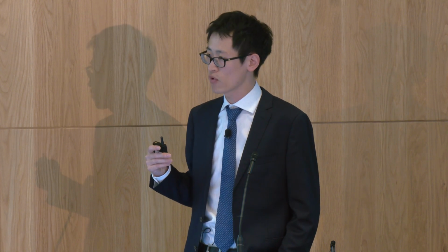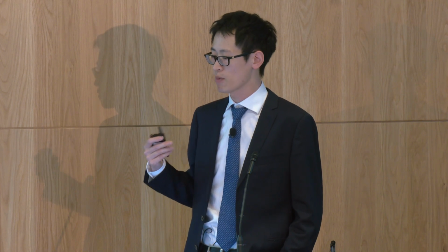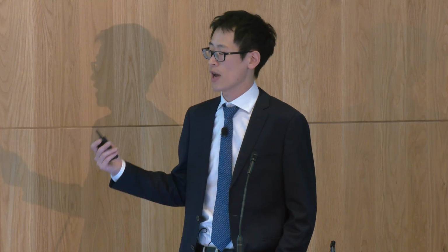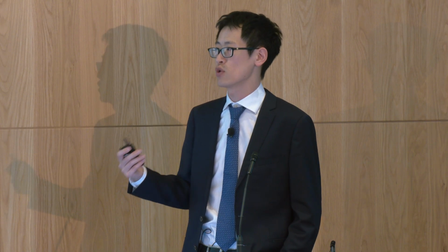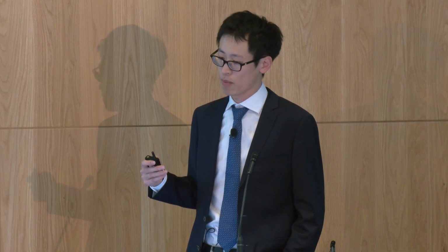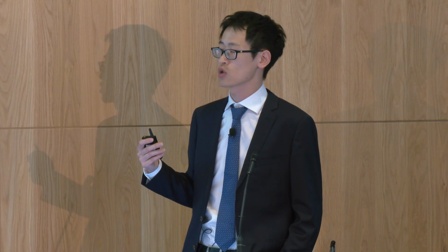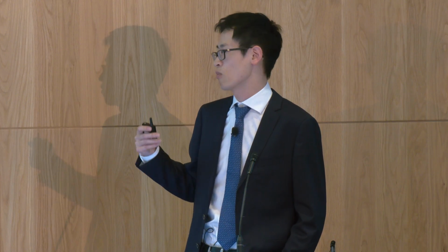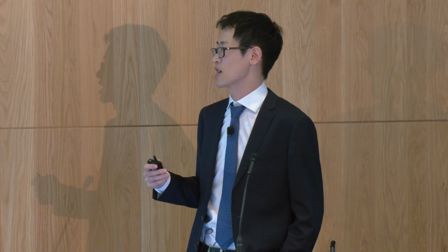From the project delivery perspective, the top-down approach is more suitable for, or commonly adopted in, the traditional project delivery process, where the module manufacturers are involved downstream of the process. If you are familiar with customer-driven production strategies, this is more used for engineer-to-order products. And the bottom-up approach is widely adopted by developers that use integrated project delivery, where the modular manufacturers are involved in the early design phase, and that is used for assemble-to-order products.